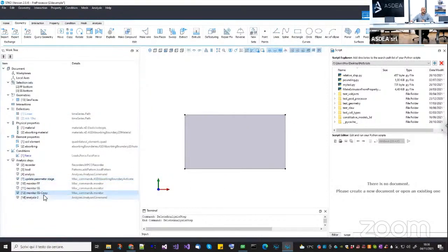Now I just want to change slightly the... Oh, we have a question. For the 3D case, the element and material are assigned to surfaces, right? Yes. Then STKO takes care of the corner element automatically. If you want to know how, you can access the source code of the element. You will see that it is quite complicated, but we managed to do it. But now you will see how STKO creates these elements.